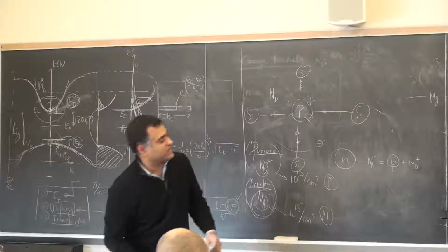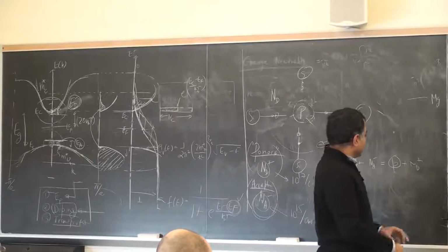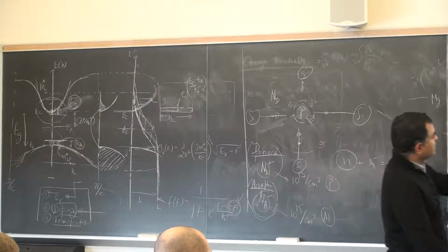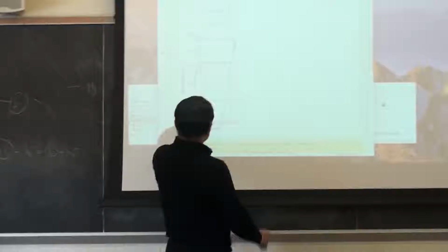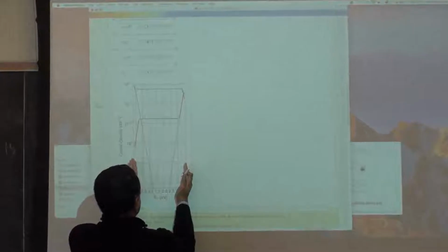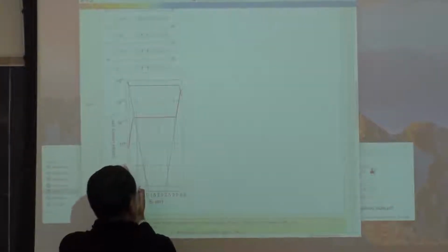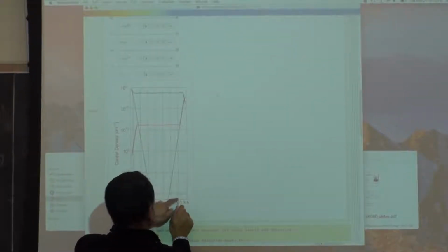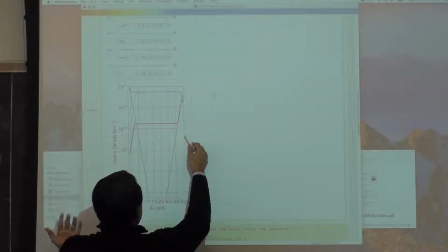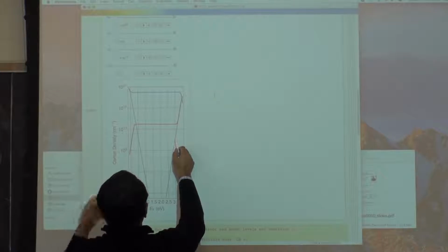Remember, N and P, electron density and hole density, don't care exactly whether you have doped it or not. That expression just depends on the Fermi level. So here's my electron density. Here's the gap of a semiconductor, 3.4 eV, that I've chosen. If my Fermi level was at 3 eV, then here's my electron density N, about this much.